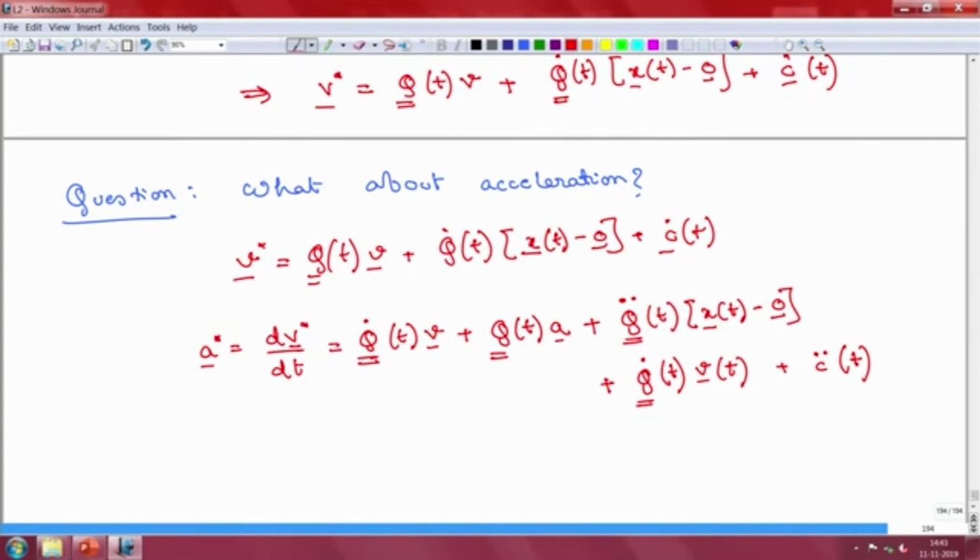Right. So, we can see that contrary to our expectation, had this been invariant, only this particular term would have been there, but we have so many other terms. So, acceleration is also not frame indifferent. Okay. So, we will make a note. So, acceleration